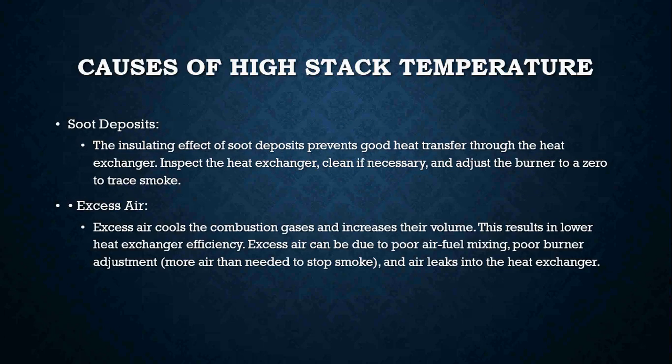Okay, what's going to cause high stack temperature? Well, the first culprit is going to be soot. Okay? Soot is an insulator. It's going to affect how good of a heat transfer that oil is going to be able to give to the heat exchanger. In fact, inspecting the heat exchanger, clean it if necessary, and adjust the burner to 0 to trace smoke. That is the best way to eliminate your soot deposits. You do not want smoke.